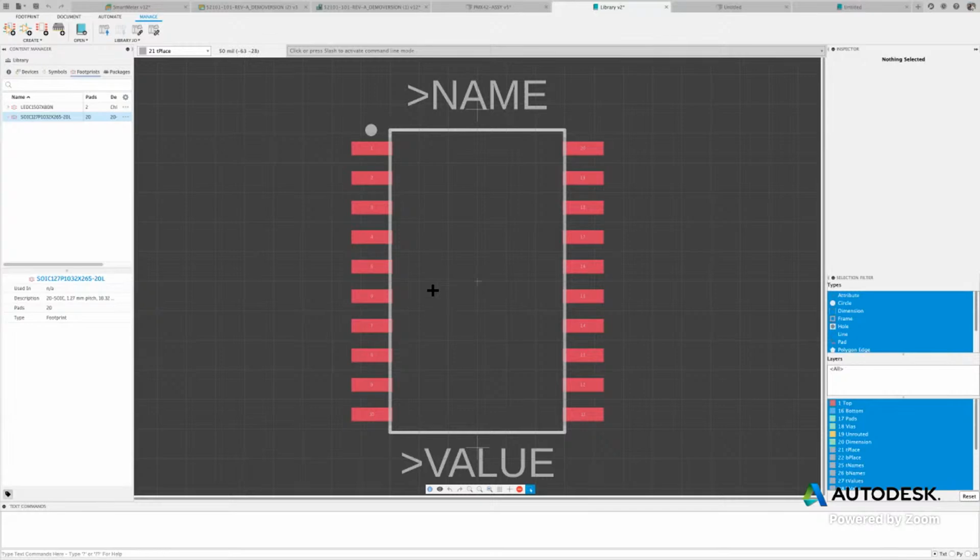Now, let's go ahead and start building our first schematic. Let's access the schematic editor, or what we call the electronic document. Remember that in the PowerPoint, I told you that Fusion 360 keeps annotation between the circuit board and the schematic editor. To accomplish this, we need to create an electronic document.